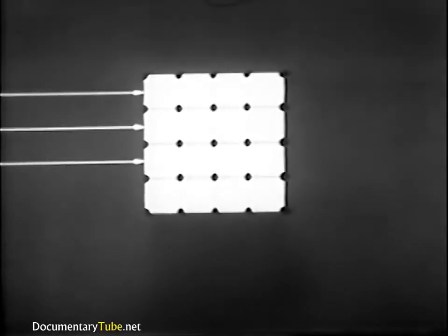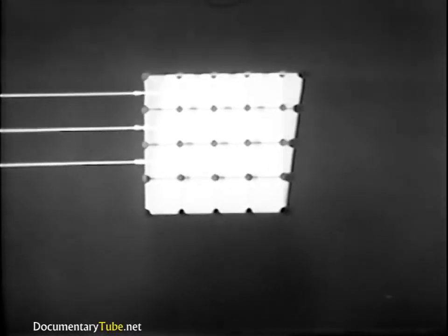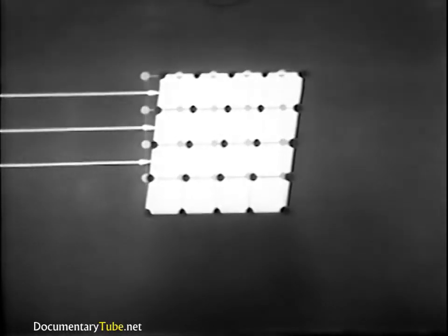The first is called elastic deformation. When small external forces are applied to the crystal, atoms on the lattice are moved slightly from their normal positions and the lattice structure is skewed. When the forces are removed, the atoms return to their original positions and the lattice recovers its normal shape.